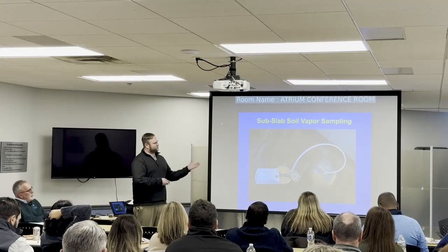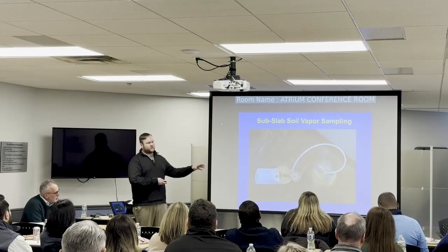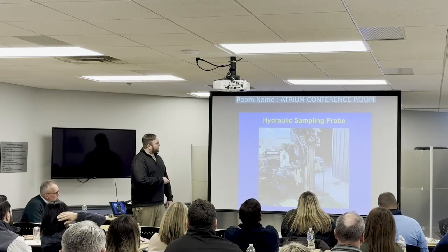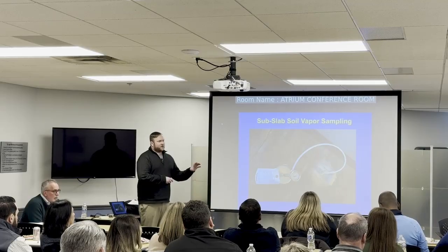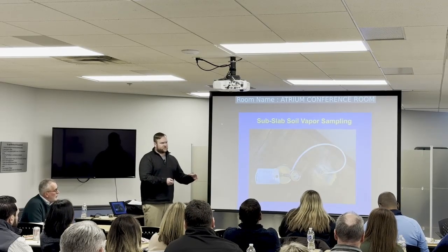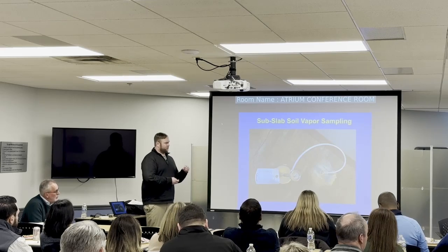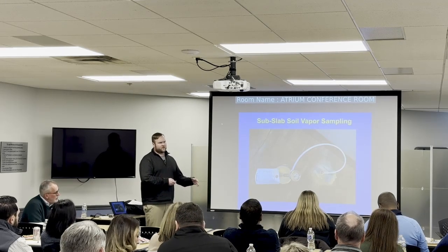So the vapor intrusion risk is really the most appropriate exposure pathway, so we decided to just evaluate that at this site. You guys just go down like below the slab? We usually try to get a few inches beneath the slab. The idea is to try to generate a void space in the substrate beneath, so you can tell very quickly when you're drilling what you're into, whether it be clay or sand and gravel.